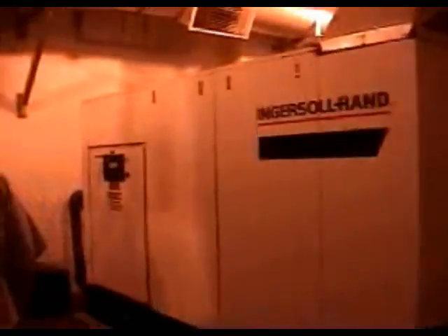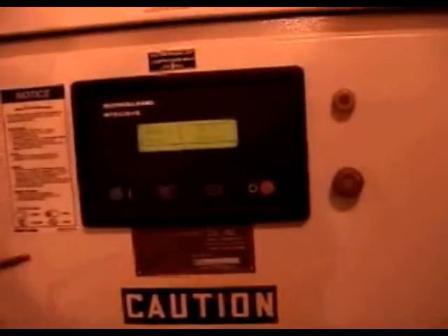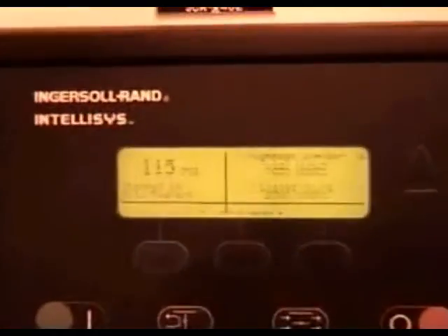These are Ingersoll Rand air compressors, and these are the air compressors we use to run air to the filters, the tertiary filters, and they also provide air to the pneumatic valves on the aeration basin. So it's really important if you have a problem here in the plant, particularly a power outage. Some of the first things you want to do is come in here, start the blower, and then come by here and start this air compressor.